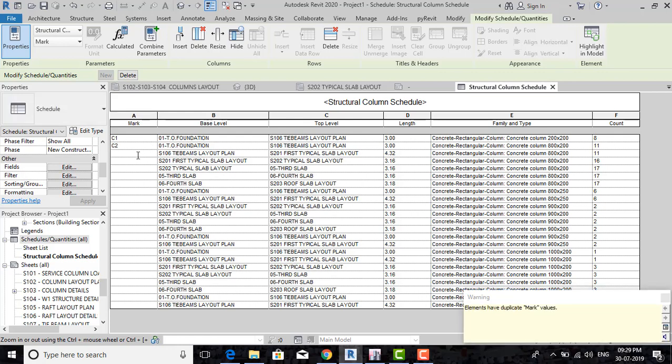See one thing: no need to put these marks in your plan and then come down here and again put marks here. Check here, it will create nuisance. Just by looking at your top and base level, you can make the mark in the column. But the important thing is this type. I'll click C4, C5. For example, I will put only up to C5. I'll just show you the example.